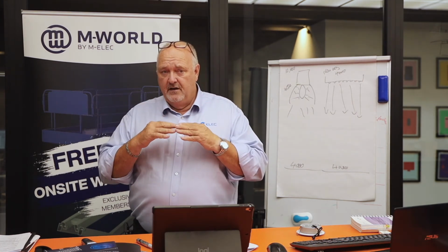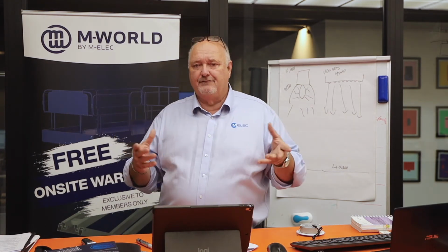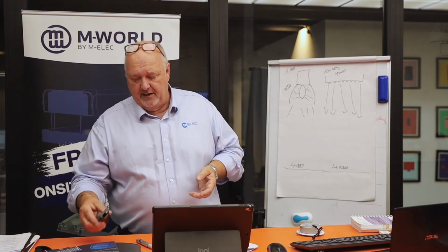All right, so that's a really important chart. Familiarise yourself with it, because it'll save you any issues or hiccups down the track, because if it's not ICF or IC4 and you cover it and the insulation is not correct, first of all, it could damage the LED. It could damage the light fitting. Second of all, you do still have that element of risk of fire or damage to the building. So just be mindful of that. It normally says it on the box, it says it directly on the fitting, so just be aware that it exists.